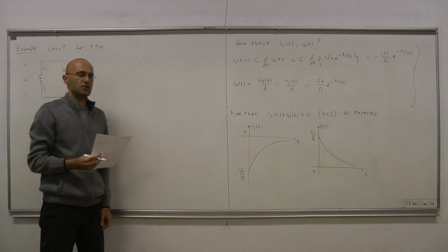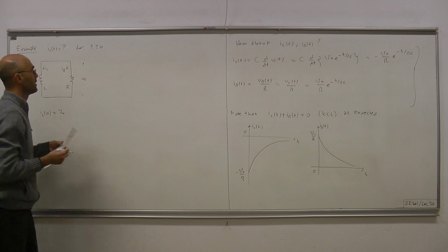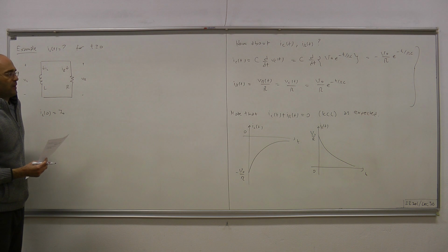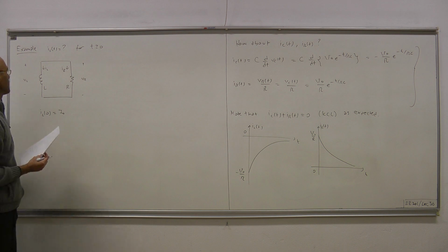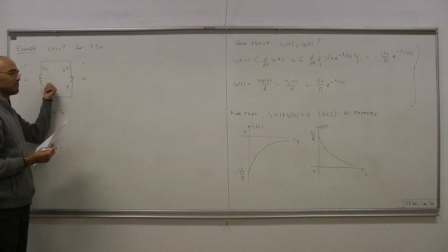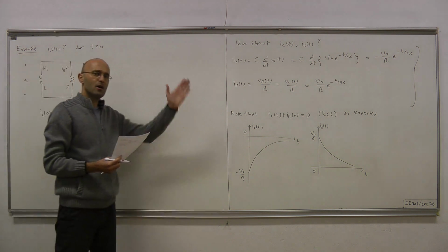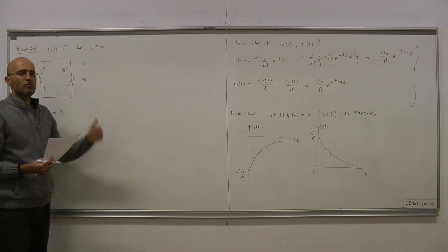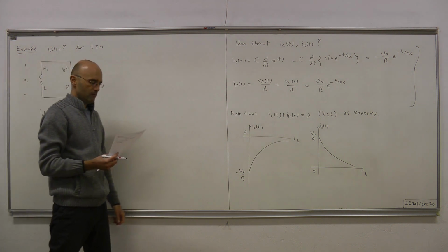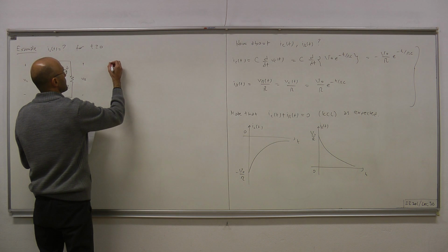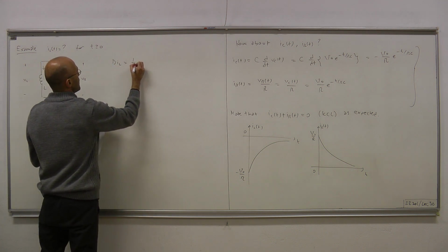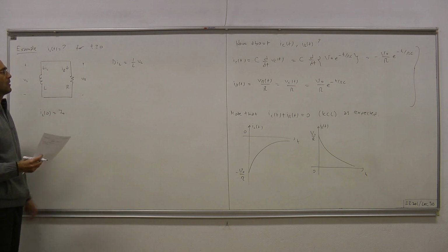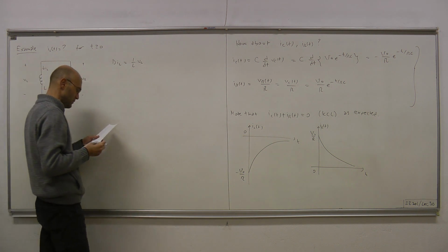I0, some constant. As before, that is, as for the case with the capacitor, we start from the differential equation or the terminal equation for the inductor, and then what we want is to obtain an equation only in terms of IL and its derivative. So dIL equals 1 over L VL. That's the terminal equation for the inductor. Now what's VL? VL is VR.